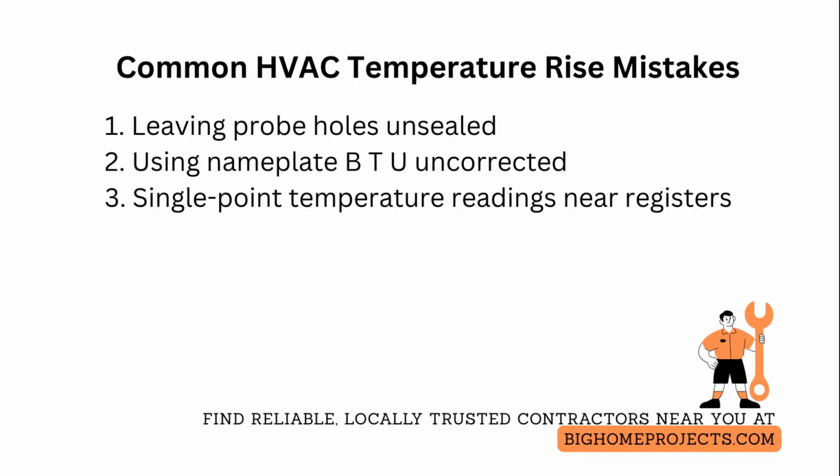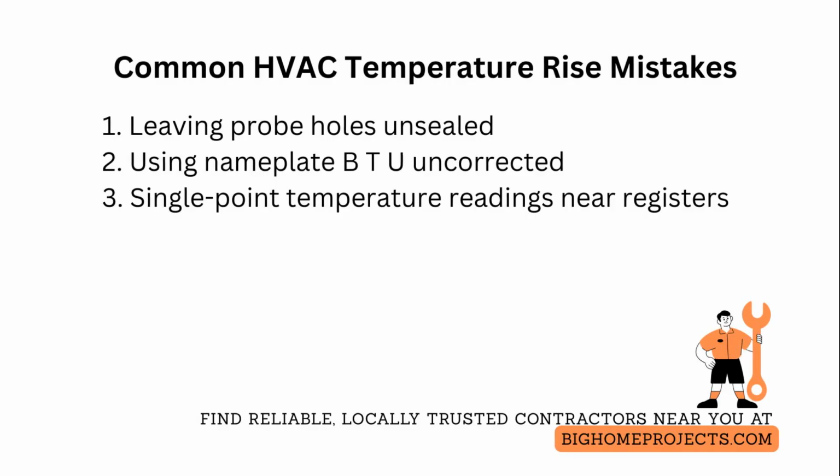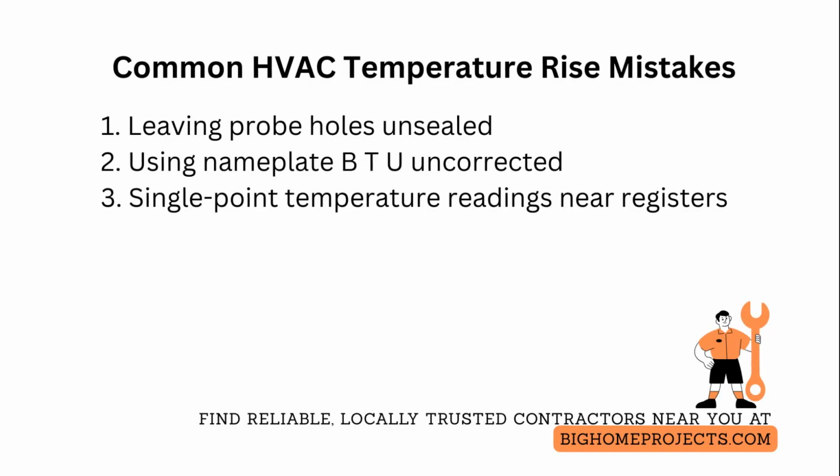use. One of the biggest issues is leaving probe holes unsealed, which causes air leaks and false low return temperatures. Fix this by reinstalling 1/4-inch zip screws into probe holes or using approved thread-in plugs, and then retesting to confirm